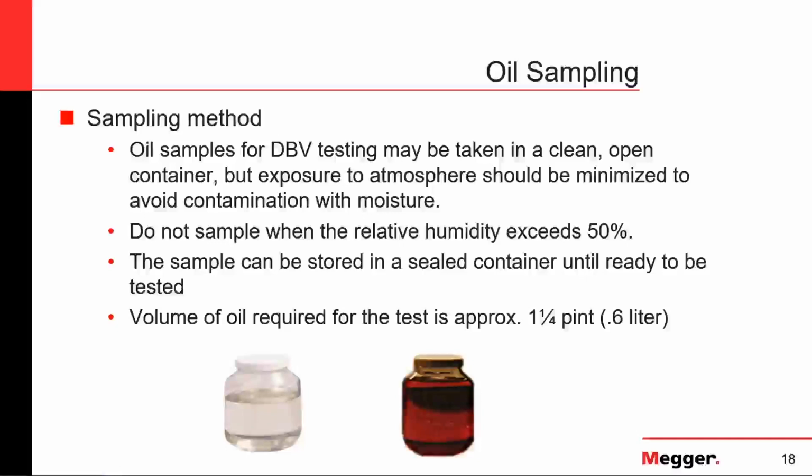It is also completely not recommended to draw samples out of energized instrument transformers and energized switches or cable termination compartments in network transformers.